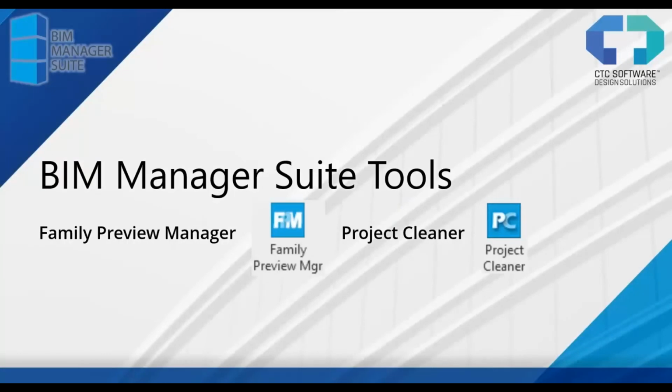From our BIM Manager suite, we've got two apps here, Family Preview Manager and Project Cleaner. Family Preview Manager is another relatively new app of ours, and this will help you generate the preview image that you see in your thumbnails for your content. Instead of making sure it's oriented to the appropriate view with the certain settings applied so you can do your save as and then never change it, we can use an app to help you speed that process up and then do them in a batch process.